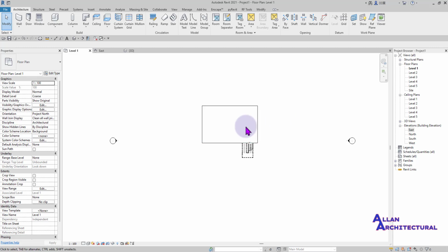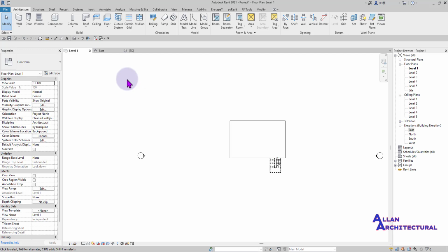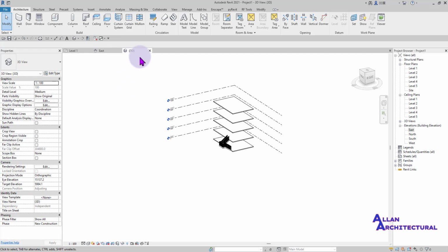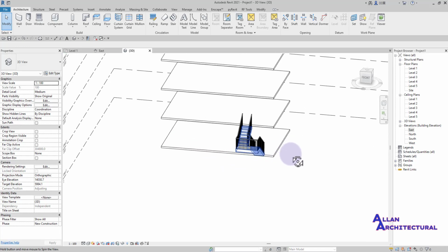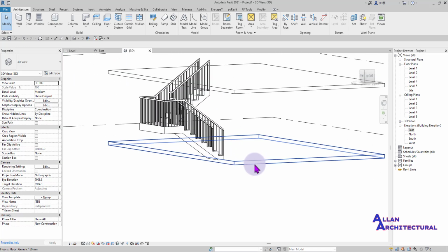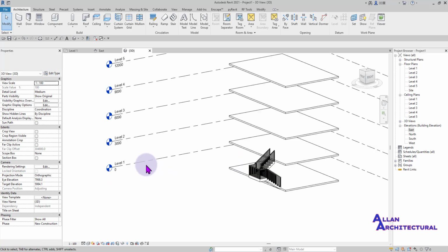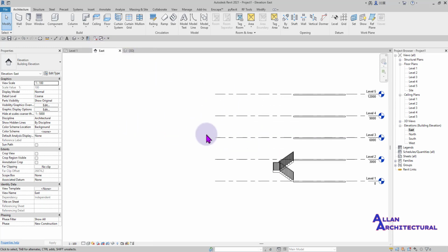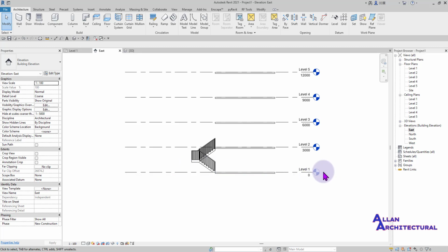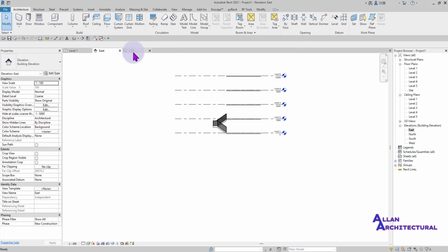I'm going to get started so we can actually find out what this stair icon really entails inside of Revit. So now I'm going to head into the 3D view so you guys see what I did ahead of time before starting the recording of this video. So I just created a floor slab. First of all, I just added more levels inside of the software. So you can see in there, you head into any of the elevation views and then you can add in more levels inside in there. So I just added more levels to get to level 5 in there,